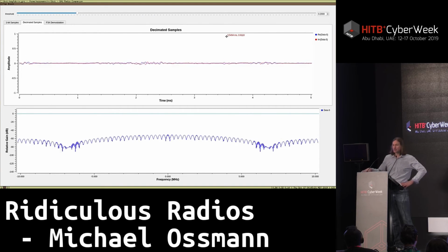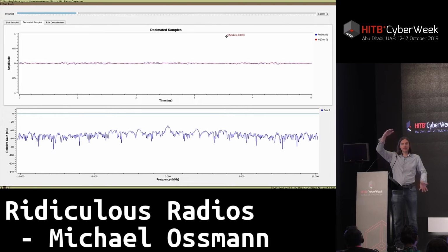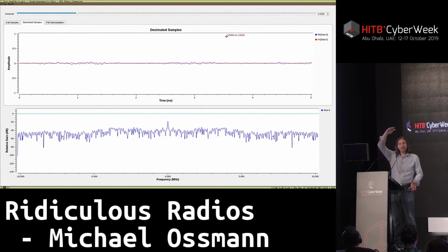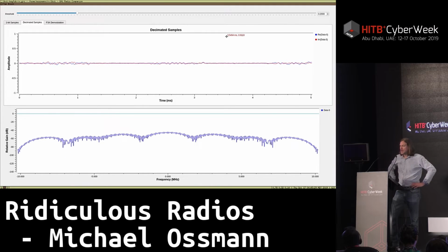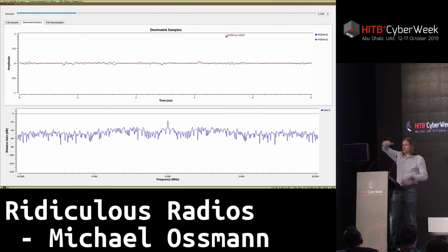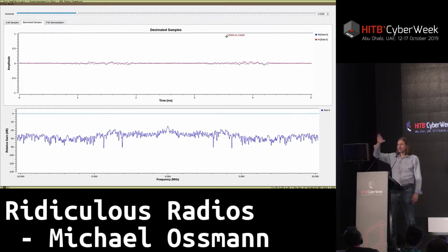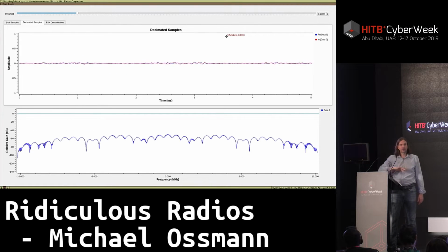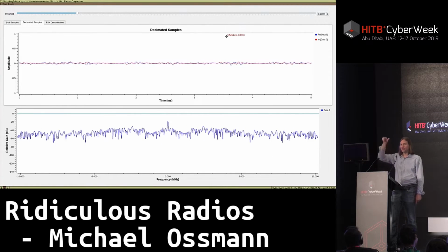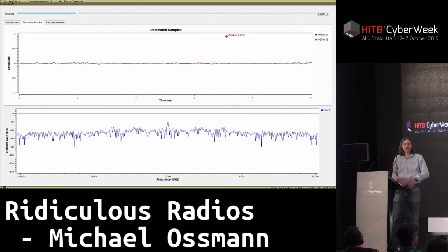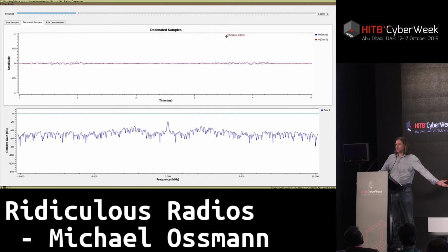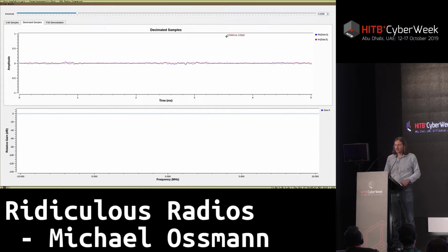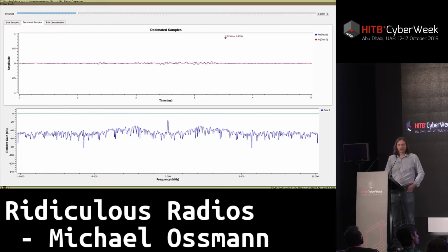And you see that from time to time, there's a signal present that's much higher amplitude than kind of the background noise that happens between these signals. And when you see those higher amplitude bursts, you'll see lots of little patterns that look very sinusoidal. They're very smooth. They're not these square zeros and ones. It turns out if we combine all these square zeros and ones through this process of decimating, we can get some pretty good looking radio signals.